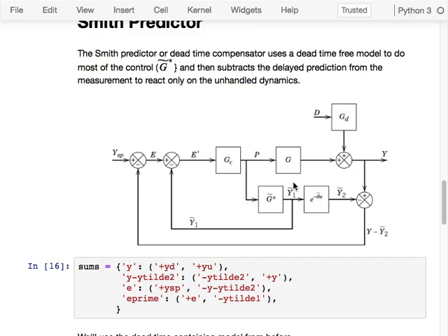And if you look at the model shape, it's obvious how you would use a nonlinear model in this structure. So if you had a high-resolution nonlinear model, this block diagram tells you, oh, well, you just take the nonlinear model and simulate the nonlinear model's response to the system, right? And you still do all the same math. You still subtract, you just act on that nonlinear model response as though that was the measured variable, instead of acting on the actual measured variable.